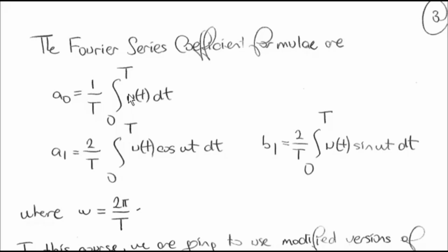So we are going to use them all the time. Here, one thing important is that I can carry out the integration over any period of the signal. So I can take the integral from 0 to T, or I can take the integral from minus T over 2 to T over 2. It won't matter because the signal is periodic with this period T. So you have to keep in mind here that the integrals can be taken over any whole period, and the limits do not matter as long as you carry out the integration over one period of the signal.